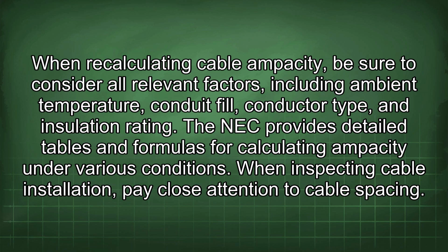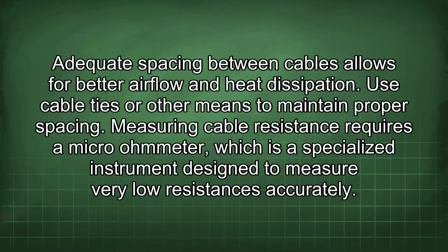When inspecting cable installation, pay close attention to cable spacing. Adequate spacing between cables allows for better airflow and heat dissipation. Use cable ties or other means to maintain proper spacing.